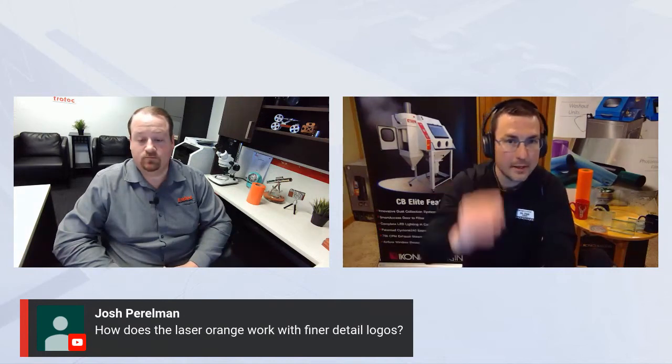Yeah, as long as you have the right media. We talk about fine grit, 180, 220 grit. The higher the number, the finer the grit. As long as you have that fine media, anything you can create in your laser, you can sand carve down the road. So 6-point fonts, that's what I recommend for 180 mesh. If you go below that, like a 4-point, you definitely need a 220 grit. But it all depends on your machine too, right?